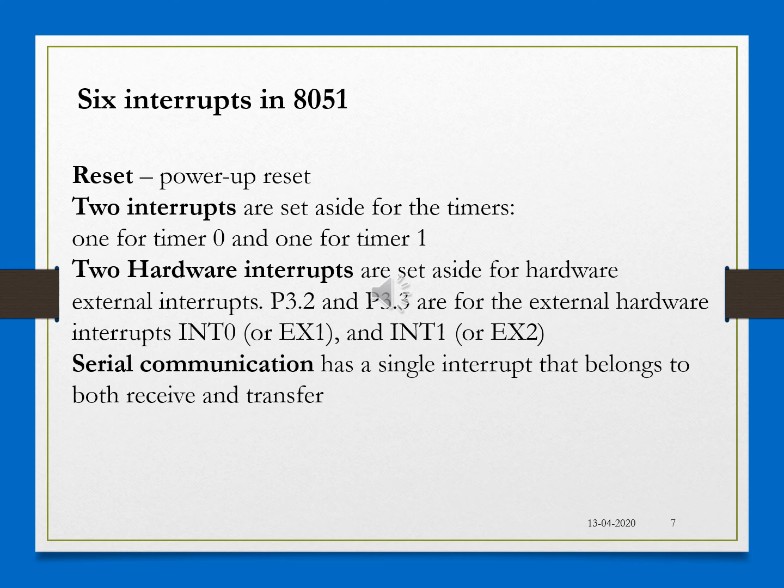The CPU halts whatever it is performing and starts again from the initial stage. When the reset pin is activated, 8051 jumps to the address location 0000, the beginning location, and from there everything starts. That's why reset is also called one of the interrupts.